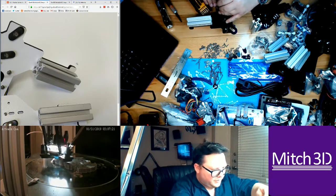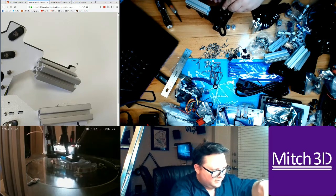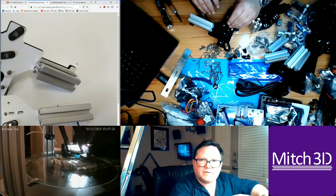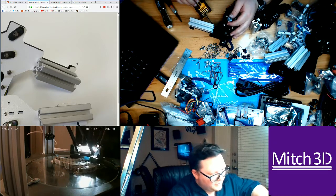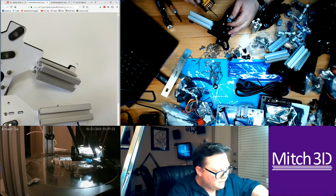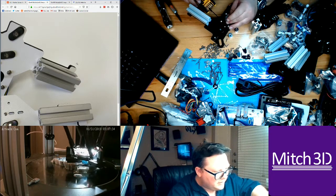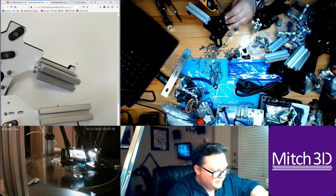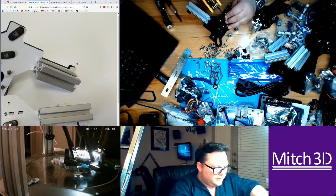Let me turn the stepper motor flat here, and I'm sorry if you can't see this. I'm basically putting the pulley on flush and trying to get it on the flat spot of the stepper motor, so the set screws don't slip.